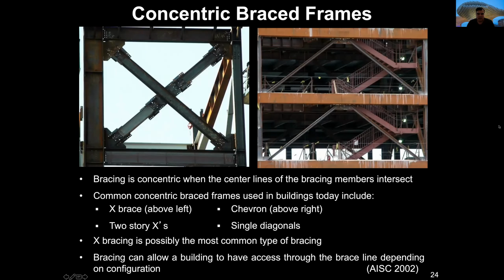There are concentric ones that are very symmetrical, where the center lines of the bracing members intersect. For example, X brace, chevron, single diagonals.